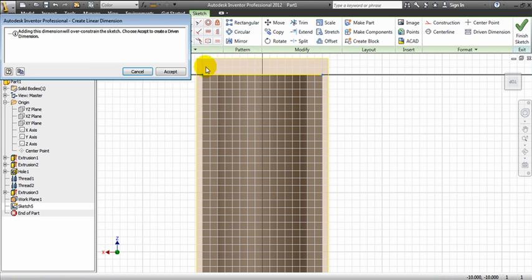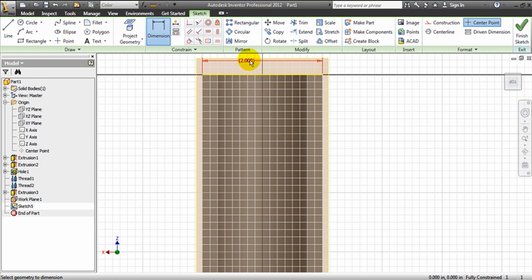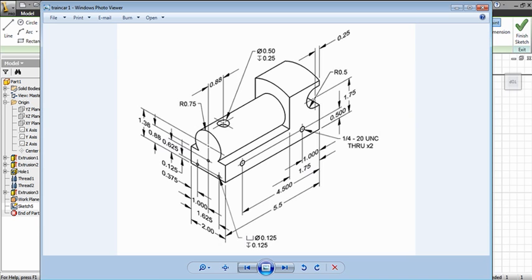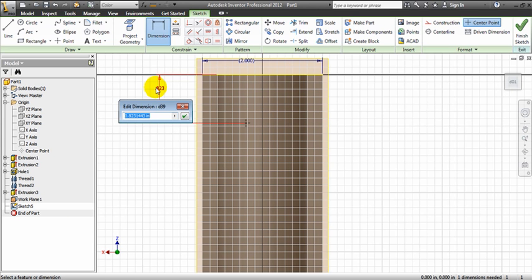I've got a 2-inch line. Very good. That's great, because I'm going to use this as a reference so that I have this thing right in the middle. I'm going to grab my point, and I'm going to click somewhere, and I'm going to dimension this from the point to the line, and from the point to the line, if you remember, is 0.88 inches. So I'm going to go back here and make this 0.88. Looking at this from the top, you remember. I'm also going to make sure that this point is in the middle. It's 2 inches across, so I'm going to make this 1 inch from here.